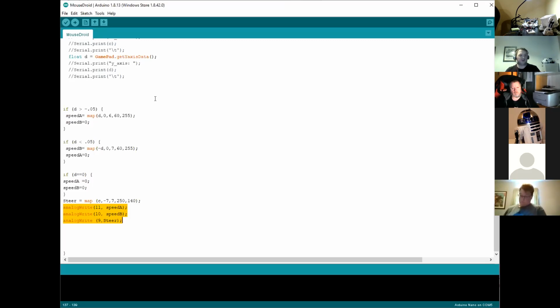Yeah, because I was looking at some stuff, and some modules want a number up to 1023. Yeah, and just bits and pieces like that. So it's just establishing where you find that number for what that particular module needs, whether it's 255 or 1023 or what sort of thing.